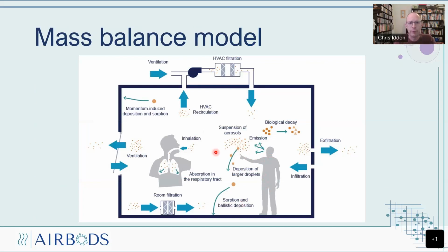But these virus-encapsulated aerosols can be removed by ventilation. The virus can be rendered unviable by biological decay, either natural decay or via things like UV light, which can increase the biological decay. And we can also use filtration to remove the particles, and some of the particles will be removed by momentum-induced deposition and sorption.